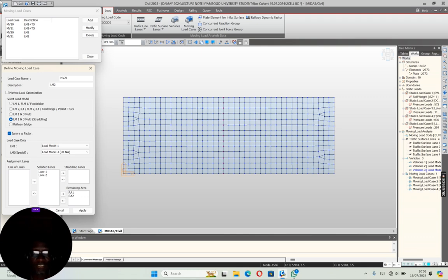We don't take the one of UK and the rest, because if you look at temperature, the Western world experiences snow loading, winter time, your temperature goes to negatives. We have never gone to that. We come down to about 15 and 17, then we go to about 35, even 37. So those are the areas we modify. We don't verbatim copy what is in a national annex. Even temperature, even wind. Your wind is extreme. Ours is not. It varies between 5 meters per second to about 25. Then with some factors, we play around there.